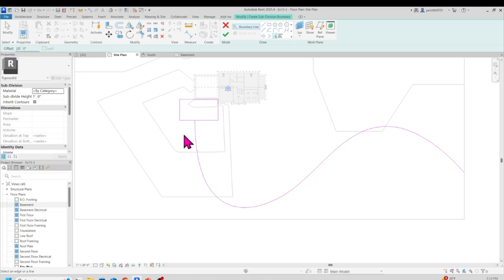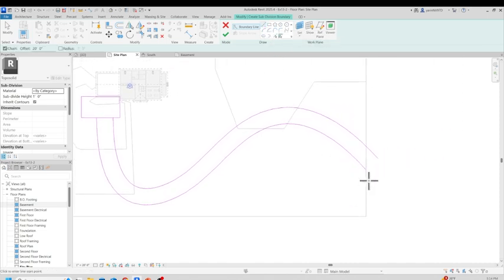So now I'm going to click on this line, which side do you want to put it? I'm going to put it on this side. So click on that, and there's our second line. One of the things is you're going to have a lot of fun with this, because sometimes this program can be frustrating. You cannot hit the check mark until this loop is closed and there's an overlap here. We've got to fix this. So I'm going to go ahead, come back, click on the line tool. See if I can put a line between these two right there.